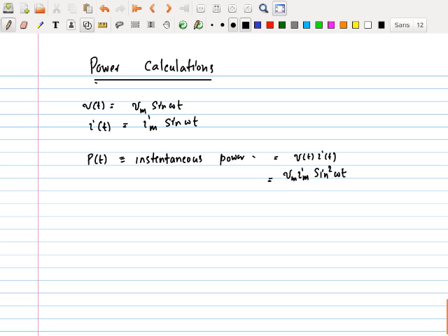Now, you tell me, if I want to find the power, now this is instantaneous power. If I give you some interval of time, and if this is a sinusoidal waveform, it so happens to be the fundamental interval of time. If I find the signal power in that whole area, what I find is the average signal power. Now, how do I find the average value of it? You integrate to find the area, and basically divide it by the interval, you get the average value.